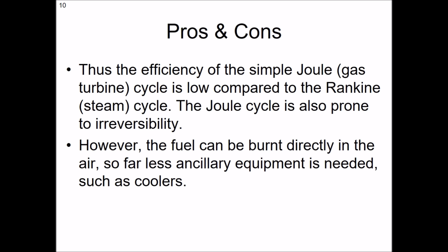You would never build a steam-powered aircraft, and I'm sure you could think of 100 reasons why a steam-powered aircraft would be a stupid idea. The advantage of a gas turbine is that the fuel and the air are in direct contact, so the system is relatively more straightforward and a hell of a lot lighter, which is why we use these particular systems. So on paper, the Brayton cycle doesn't look good, but in real practicality, it's probably one of the best options for things like propulsion or large-scale gas-fired power generation.